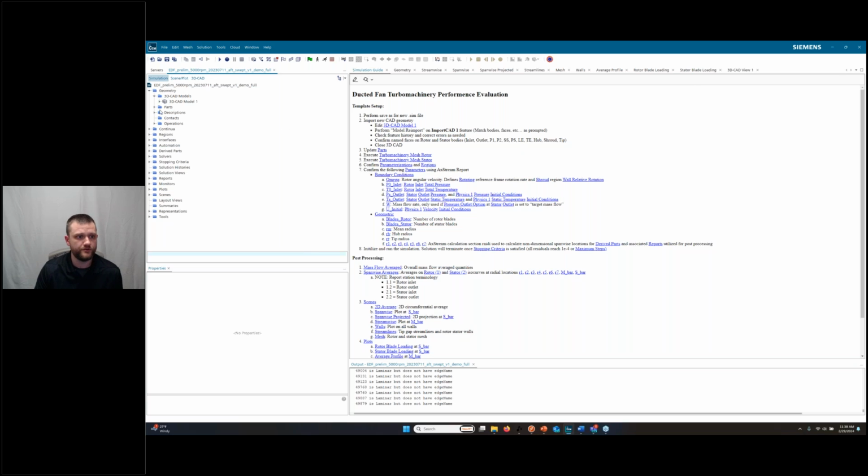If I import a new geometry, I have my parts that come in here, and everything is completely tied back to my 3D geometry. And using these surfaces, I have on each one of the rotor and stator, which are really the primitives of the turbo machinery geometry: hub, inlet, leading edge, pressure surface, suction surfaces, my periodic regions.